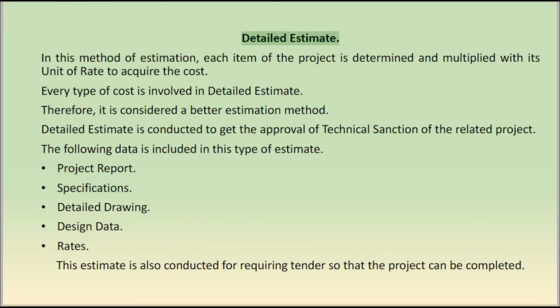Detailed estimate. In this method of estimation, each item of the project is determined and multiplied with its unit rate to acquire the cost. Every type of cost is involved in a detailed estimate. Therefore, it is considered a better estimation method.